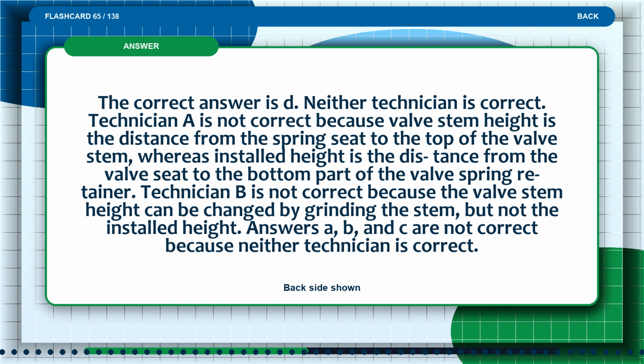The correct answer is D. Neither technician is correct. Technician A is not correct because valve stem height is the distance from the spring seat to the top of the valve stem, whereas installed height is the distance from the valve seat to the bottom part of the valve spring retainer.